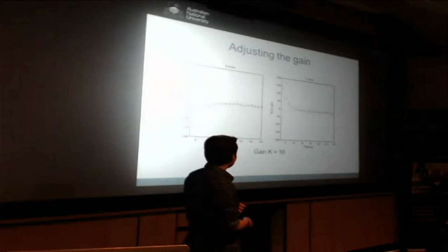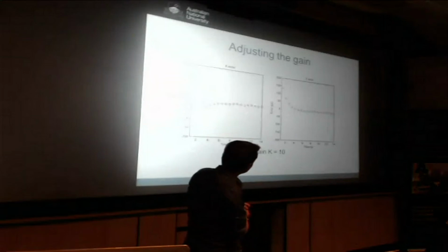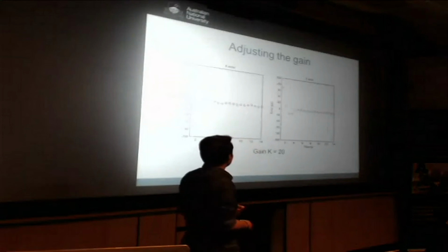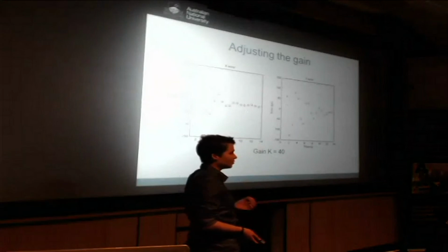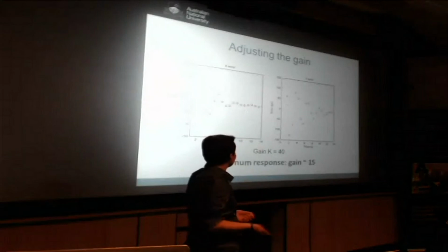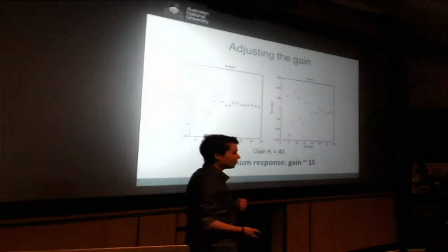As we increase the gain, the system becomes more responsive, but we also start to see slight oscillations in the response. If we increase the gain even further, we see overshoot, and if we increase it too far, the response becomes dominated by these oscillations, and the control system is almost unusable. So after analyzing plots like these, I ascertained that the optimum gain was about 50.